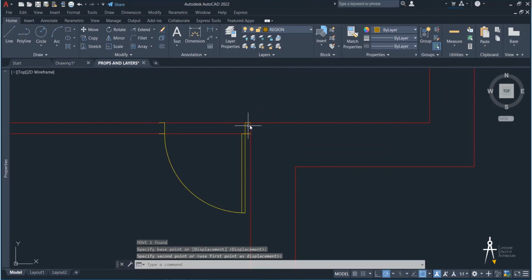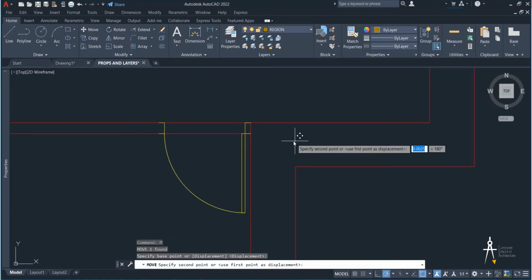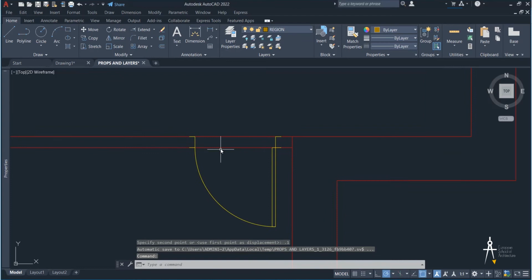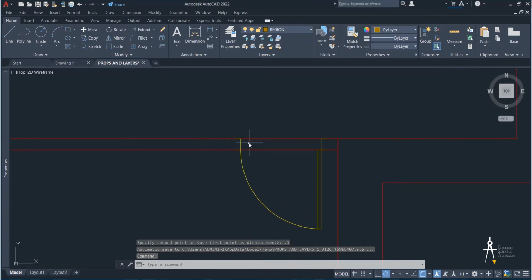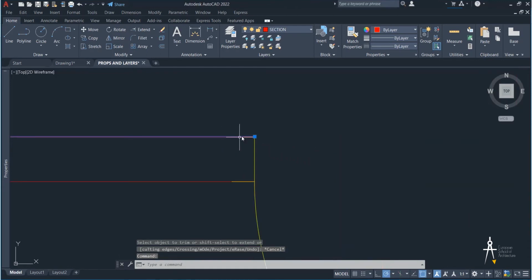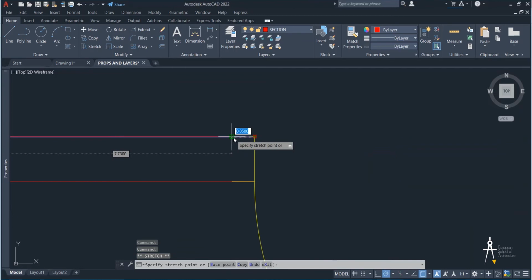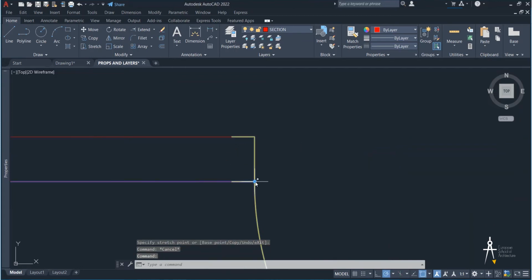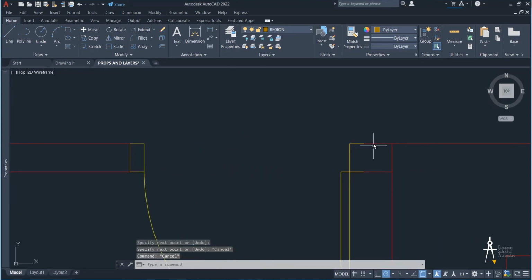Okay, first we're going to move this. You would never have this, so against this wall. We're going to move it 10 centimeters over this way, and now I have to get rid of this, right? So I'm going to say trim and off it goes, but it hasn't gone. If I click on this line, it's taking it up to this point, and it's very important that you make sure that these lines don't overlap, otherwise you may have problems when you plot, as I said before.